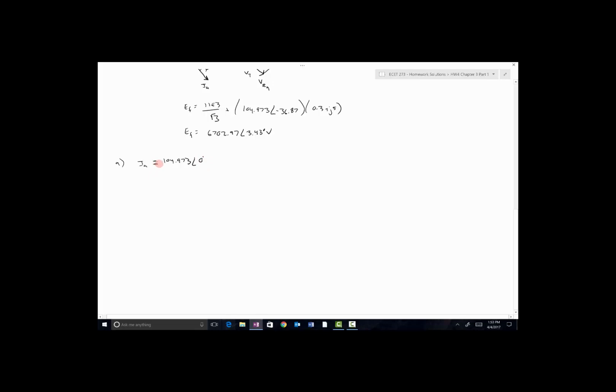So I'm going to real quickly draw the phasor diagram for that to illustrate this problem. We've got the terminal voltage VT. This is in phase, which means the voltage drop across the resistor VRA is in phase with IA. Should have drawn IA first, sorry. VT and IA are in phase, therefore VRA is also in phase.